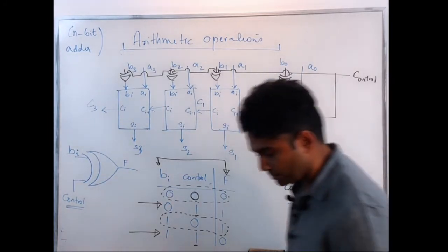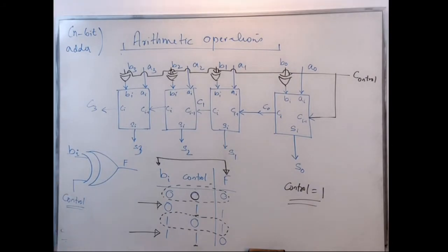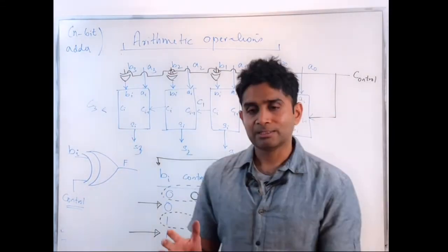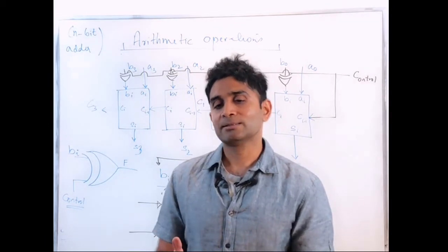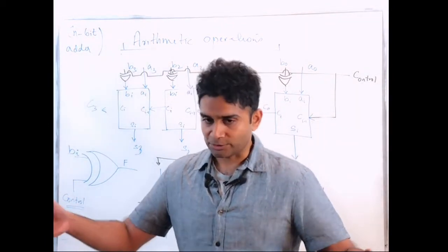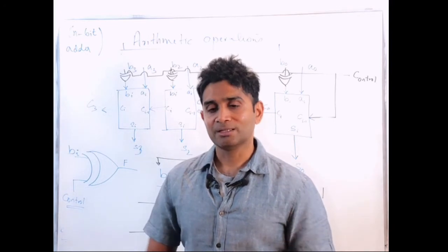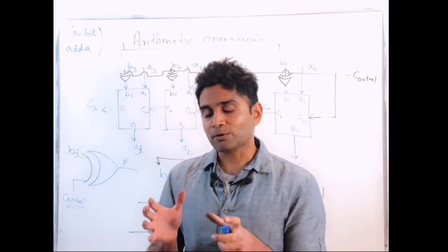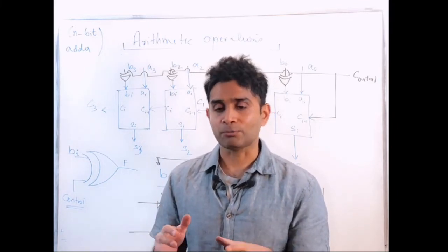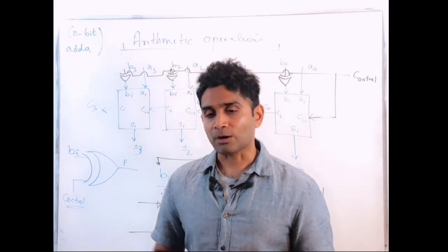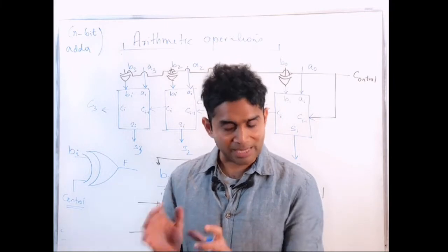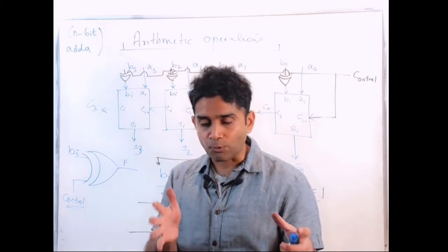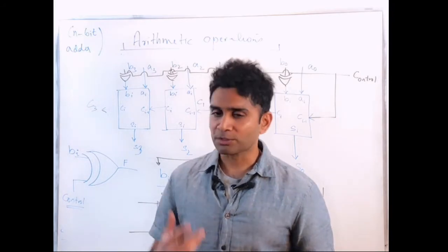Any questions on this? So again, the design principle is every time you want to design a single piece of hardware that can perform multiple operations, multiple functions, then you have to come up with a control input. If I design a circuit that can perform 4 different operations, the same piece of hardware reconfigured to perform 4 different functions, how many control inputs should I have?